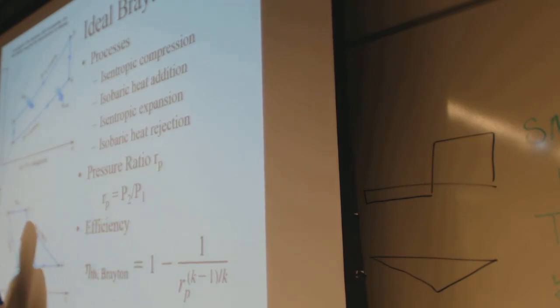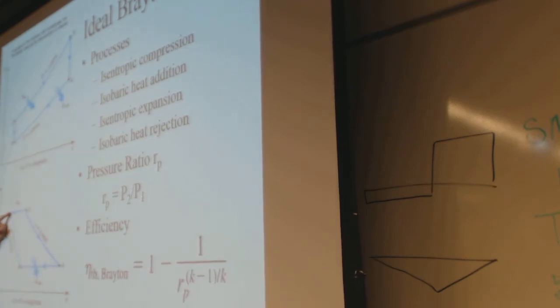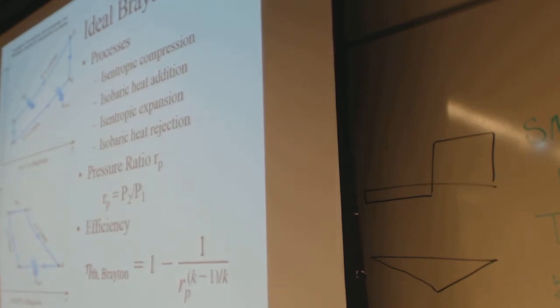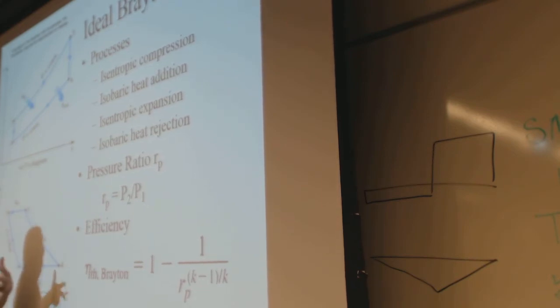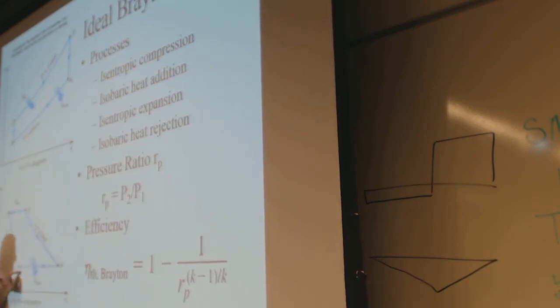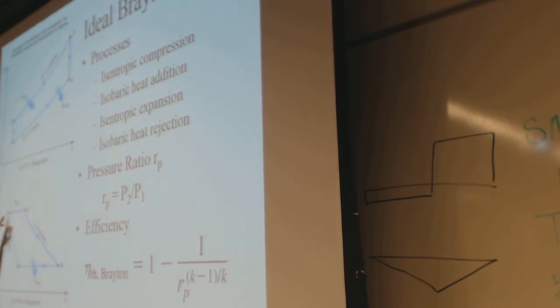So it's a constant pressure heat addition, a constant pressure heat loss, exhaust, isentropic compression, isentropic expansion. It's an air standard cycle. We're using ideal gas. So between here and here, it's a ratio of pressures. And the amount of enthalpy between those two is C sub P delta T. And what's the delta T?